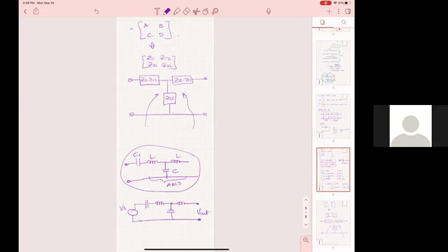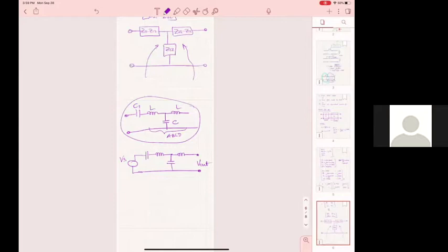That will be the best way to find out how that operates, whether it has resonances. It has resonances, we know that, because it has 2 inductors and 2 capacitors. Even if the inductors are identical, you cannot sum them up because they are on opposite sides of the capacitor. So you know that there will be multiple resonances, but because there are multiple, you don't know how that's going to operate overall.